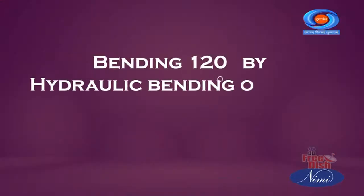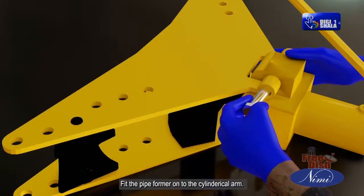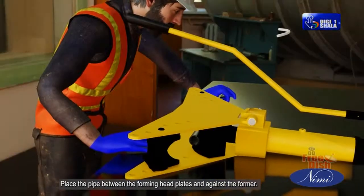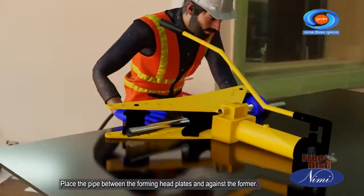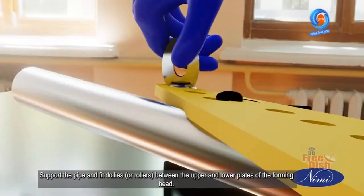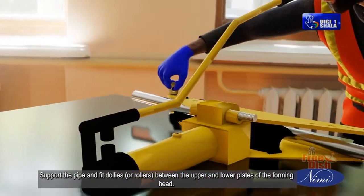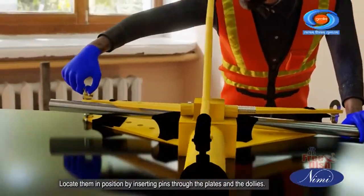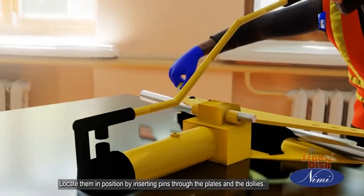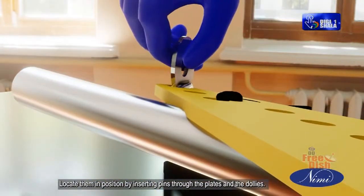Bending 120-degree by hydraulic bending machine. Fit the pipe former onto the cylindrical arm. Place the pipe between the forming head plates and against the former. Support the pipe and fit dollies or rollers between the upper and lower plates of the forming head. Locate them in position by inserting pins through the plates and the dollies.